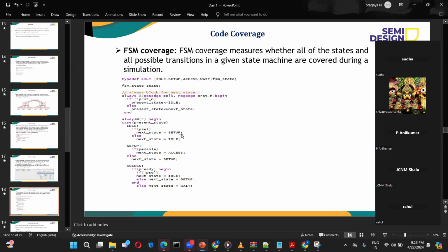Okay, this requirement is not there, so we don't need this. Or there could be some special cases. You may think that this is some priority feature you would have observed in the test plan, and everyone is focusing on that. Then you have to note it down in your coverage plan: this thing I need to sample, this thing I need to cover, this scenario should be covered at any cost. If you note it that way, you will not miss the important things. So that's how the coverage plan is done.